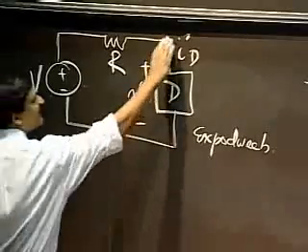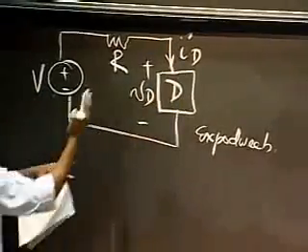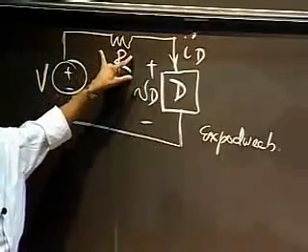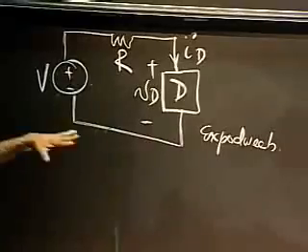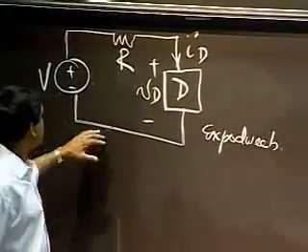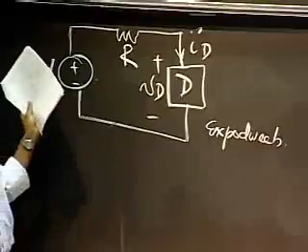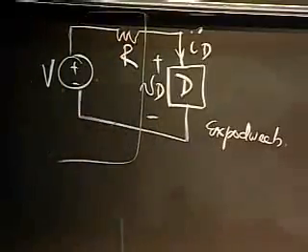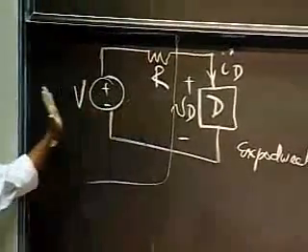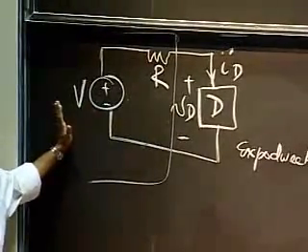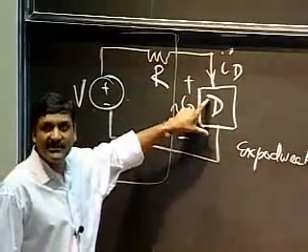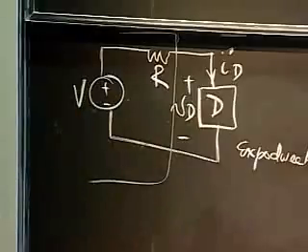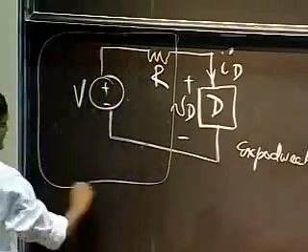In particular, if you look at this nonlinear device, facing the nonlinear device is a voltage source in series with a resistor. Now the reason I say that this is an incredibly important pattern is the following. Notice that if on the left-hand side I had any linear circuit, and I had a single nonlinear element in that circuit, notice that by a Thevenin reduction that you've learned, you can take this entire mess.